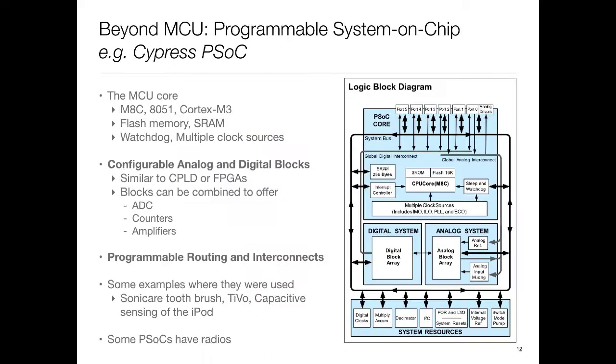Okay, so I mentioned earlier that there are these programmable systems on chip. You can think of these as MCUs together with the stuff that would have gone on the board, like the sensors, and analog circuitry also sitting there. An example is the so-called PSoC from a company called Cypress, but there are a few others.